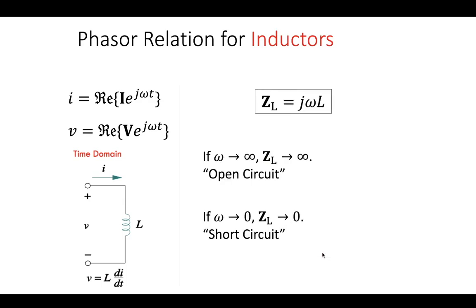One more thing to note before we end this video is that when the frequency approaches infinity, we see that the impedance will approach infinity, which is an open circuit. And if the frequency approaches 0, then the impedance approaches 0, which would make this a short circuit.